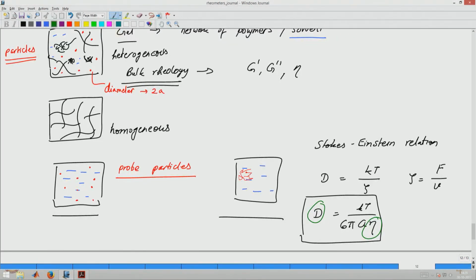So, therefore, viscosity can be measured. Now what can be done is we can focus on a set of particles in different regions. In a heterogeneous case, in certain regions the particles are facing fluids of higher viscosity, and in some other regions the particle has a region of lower viscosity. So you can look at how many particles are showing a higher viscosity region, how many are showing a lower viscosity region, and get some idea of the heterogeneity of the sample.